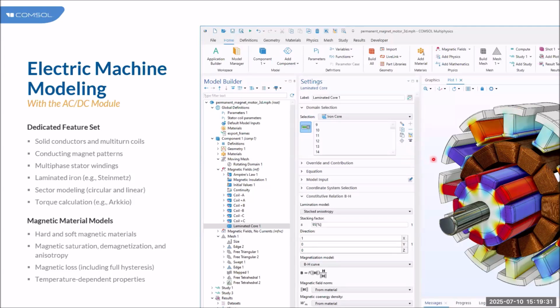And in terms of laminated cores, how much loss is happening in the laminated cores, we can visualize, or we can use the empirical formulas available, which are used mostly in industry, like the Steinmetz formula or the Bertotti equation, for defining the losses in the laminated core when we are going through the workflow. Apart from that, these are the magnets involved, which are placed here, like a number of permanent magnets on this rotor. That is why it is becoming a permanent magnet motor, and it is a 3D version of this one.